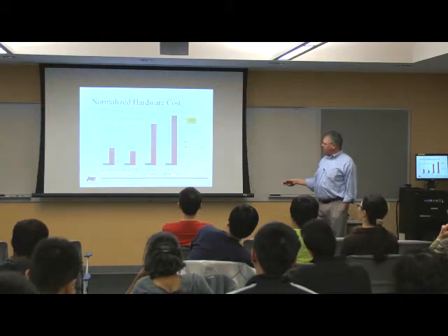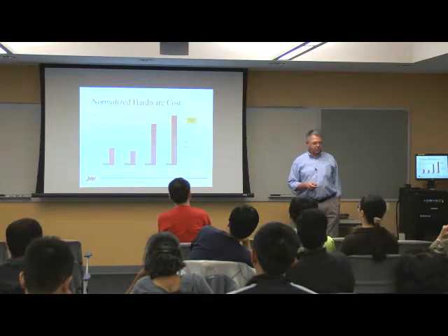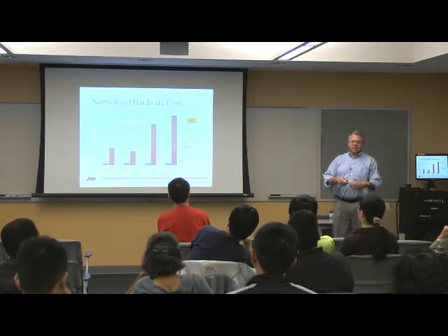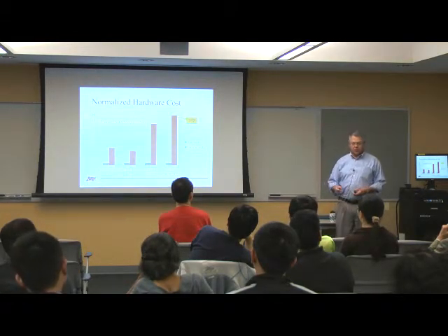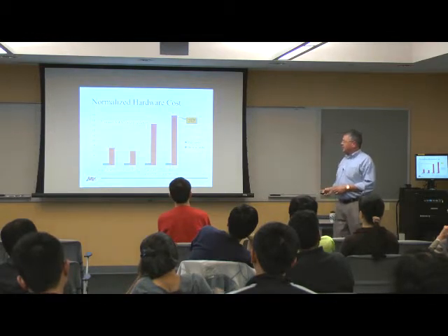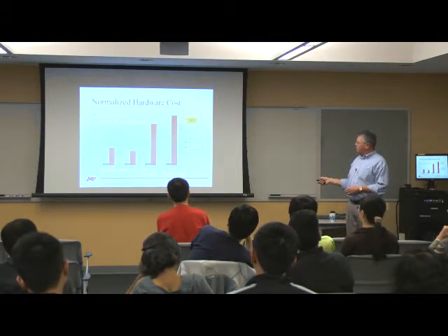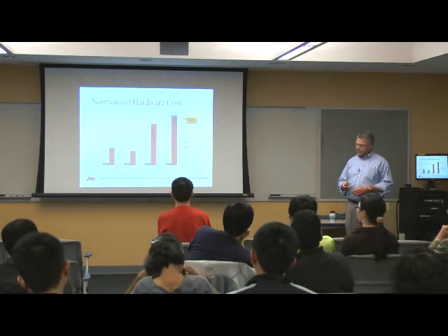The KDE segmentation is 267 times more hardware than the conventional implementation, which makes sense. To implement exponentiation conventionally requires a lot of hardware. Here I do it just with those thresholding circuits and those stochastic adders, so I'm much, much cheaper in the stochastic implementation. All right?